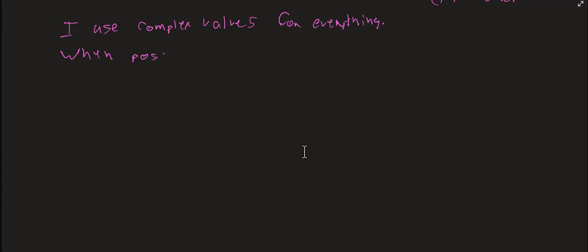When possible, I use S equals 1/2 V I conjugate. That's almost always possible, and it is always correct. I mean, the 1/2 might not be needed, you might make a mistake somewhere, but you can always use it.